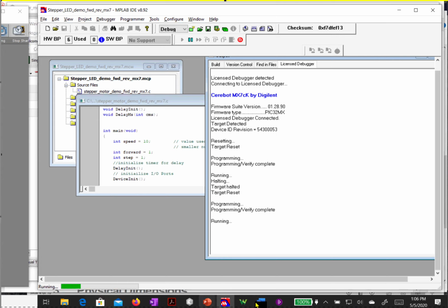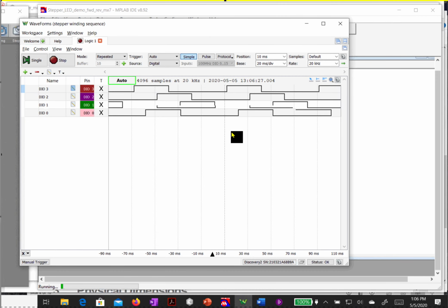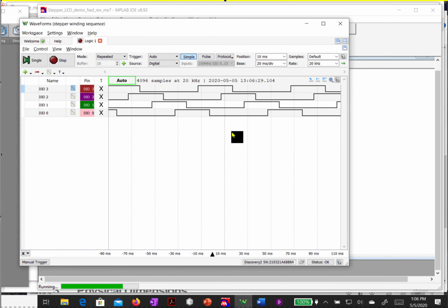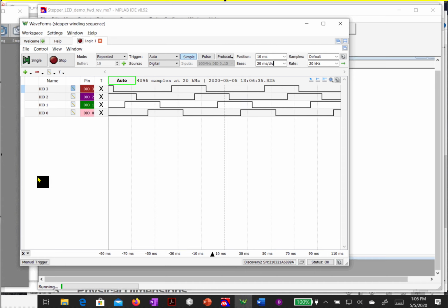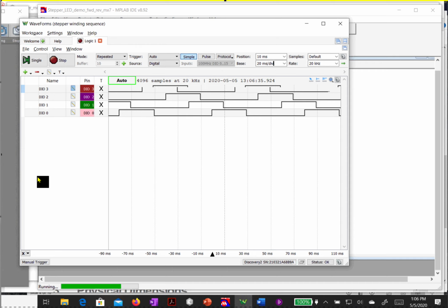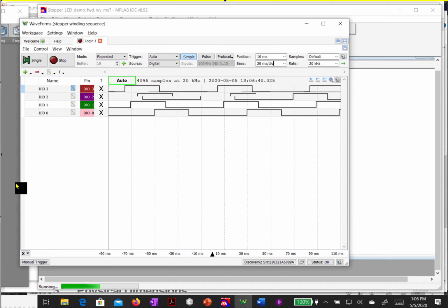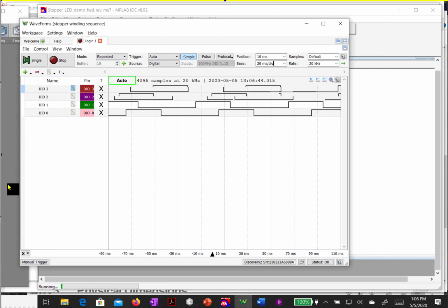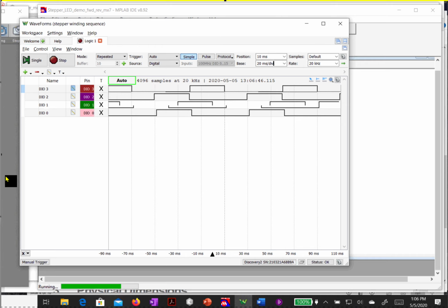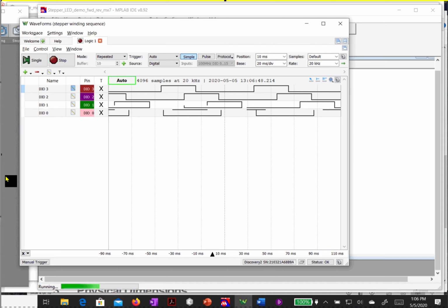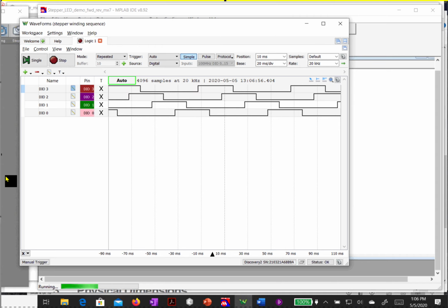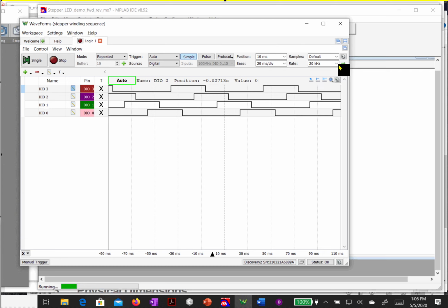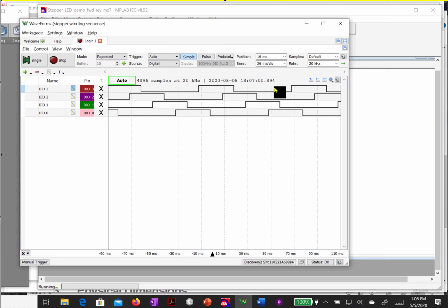And so these stepper motors, as we see, we can position very, very accurately. We can control speed very, very accurately, but the way that we energize them is different. So we see that the way we're actually driving those signals is different, and that we're energizing 4 signals simultaneously. And so by doing this, we're able to get a full 360-degree range of motion. And of course, it takes us 4 port outputs to be able to drive this. So if I wanted to drive many motors, then I would need a number of output port signals, which I can do. It just precludes me from using some of the other devices that I might potentially want to use.